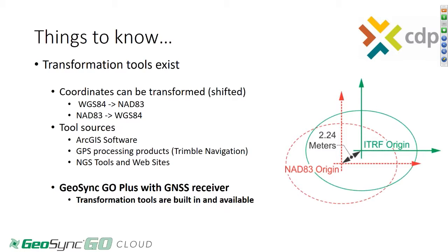You only really need to do that if the data that you're looking at needs to be sub-meter or better. Typically, that would be the dividing line. If your project scope requires you to deliver data in sub-meter or better, then you need to be aware of what is the output of the mapping that you've done. Is it in WGS84 or NAD83? And then, depending on what that output is, you need to decide whether that matches your deliverable or not.